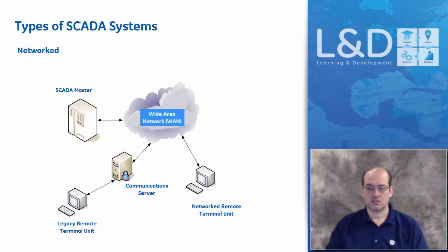Where the future of communication is going is to improve the information that's received by the utility, in order to look at very detailed information like phasors, and how synchronized phasors between parallel substations would give the utility operators a better idea and information in resolving the utility network power swings and react to it in a more effective manner than if the operator is sitting with hourly information and responding to only hourly reaction instead of millisecond reaction response.